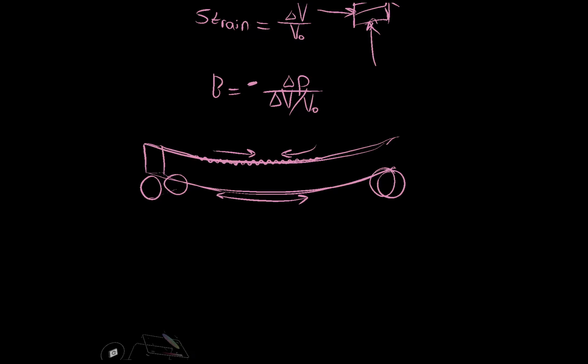So it's experiencing both tensile stress here, and at least compressive stress there. And so, consequently, the top of the beam needs reinforcement from the compressive stress up here. So you'd want this top part extra reinforced, right? And you want the bottom part extra reinforced so it doesn't break under the stretching force down there.